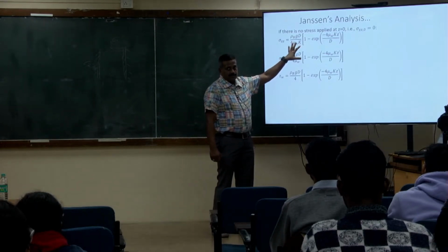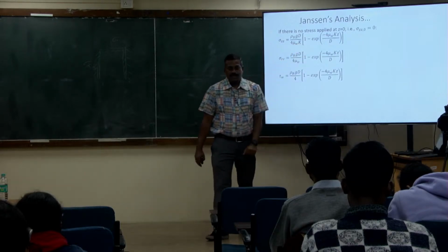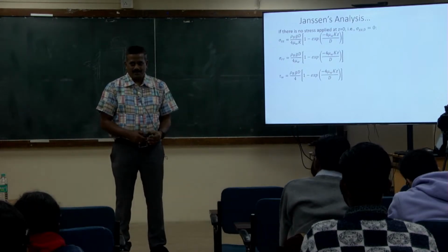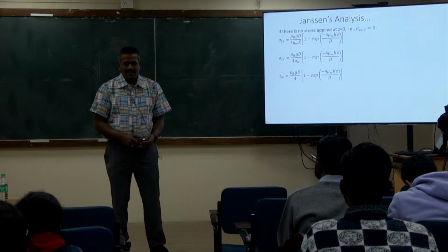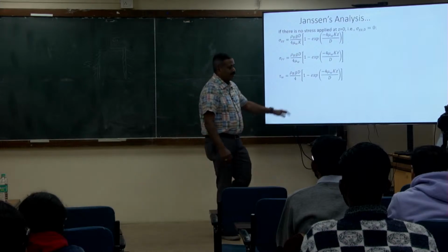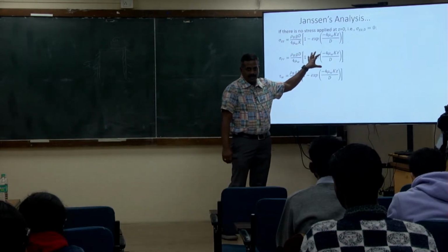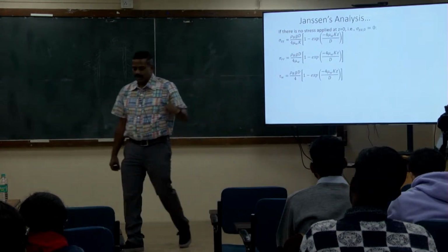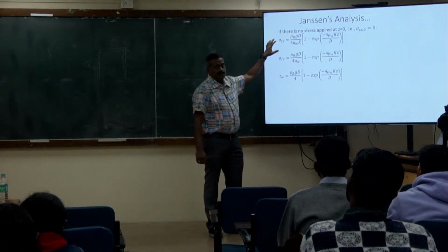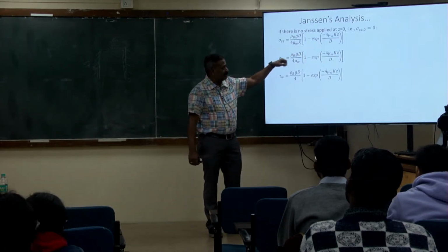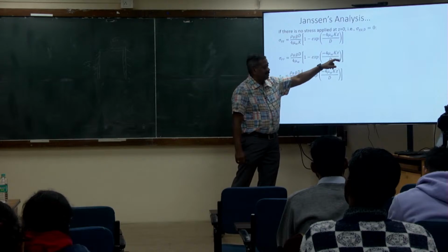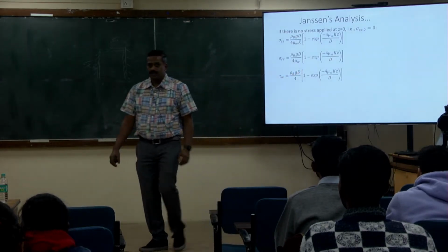It's calculated from the angle of internal friction, right? Anyone remember the formula? Okay, sine phi, it's not sine theta, just a small correction. That's 1 minus sine of the angle of internal friction, which is where we use the angle of internal friction to calculate the pressure ratio, K. So you calculate either one of them, and then using the pressure ratio K, you calculate the other stresses, either vertical or radial. Mu is the coefficient of friction, Z is the height from the top surface.